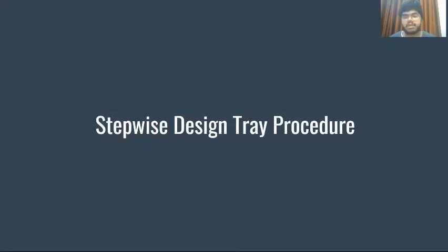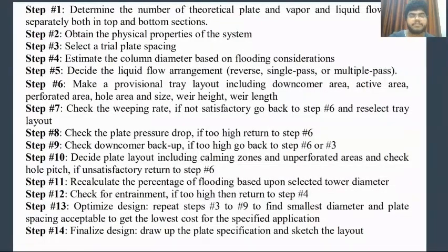However, the vapor flow rates have the highest impact on tower diameter. For example, the sizing calculation is performed on the top tray for the above feed section and on the bottom tray for each feed section for a single feed and column height. Lower tray spacing is desirable to minimize construction cost by checking against the column performance criteria. So now we will see the stepwise column design.